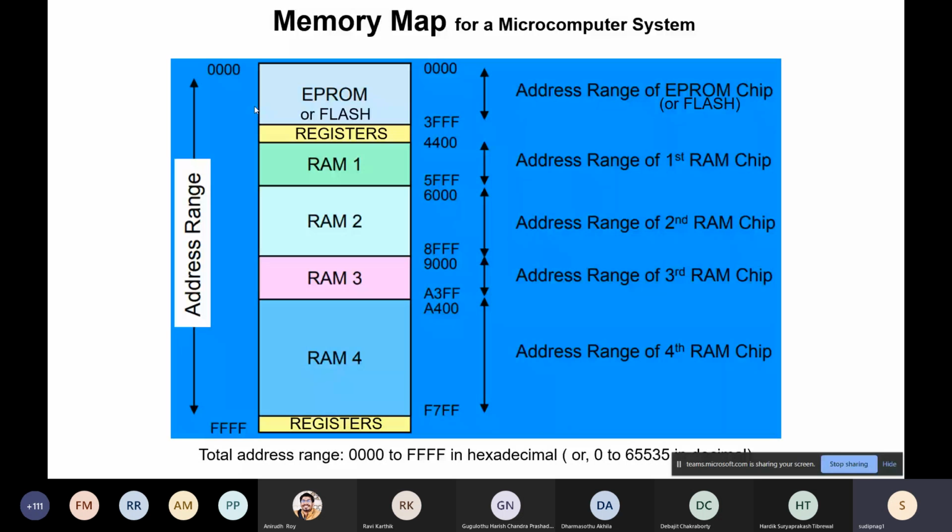That is binary level information or system level hardware configurations or very intricate internal details of hardware. For example, a MAC address is low level information or a low level setting, but an IP address is a relatively high level setting. So those kinds of low level settings are at 0 onwards in certain microcontrollers. Yes, question? Does this also include the vector table and those things? Exactly. There are some vectored interrupt tables, different types of service tables, and also where RAM1 starts, where RAM2 starts, and so on. That kind of information is also stored in the first few locations.